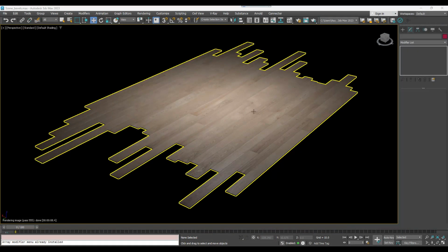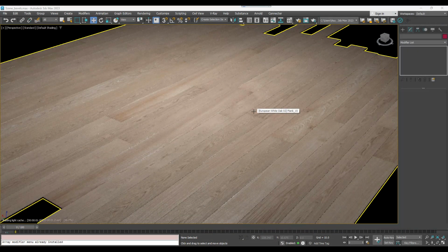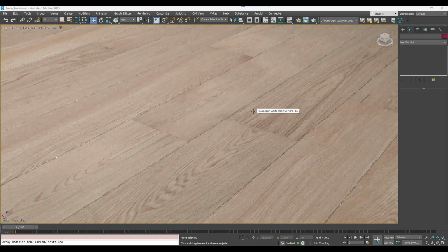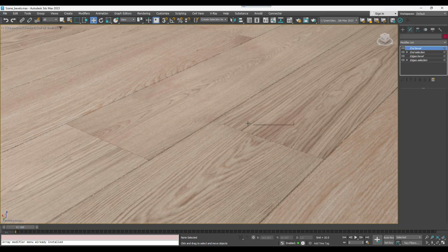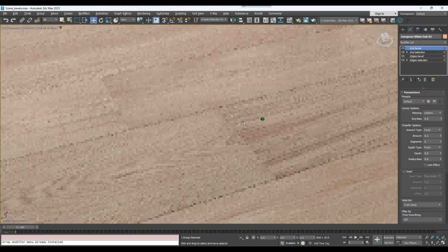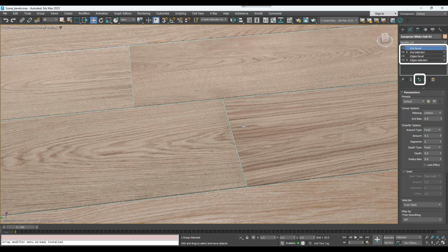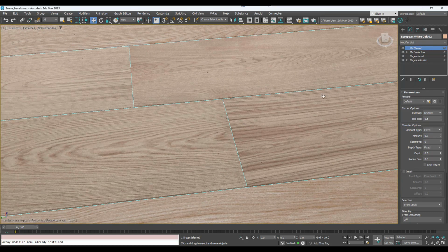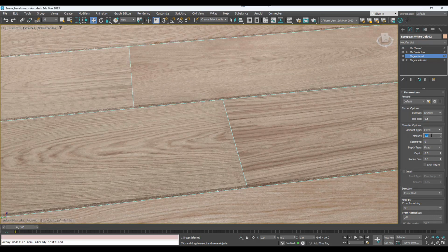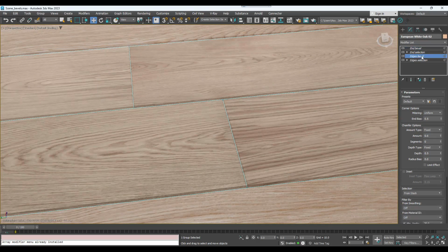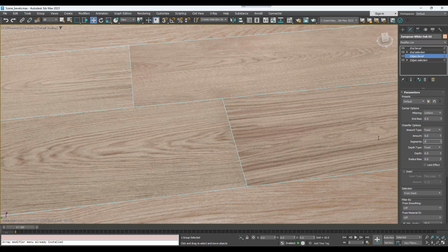The design-connected wood floorings allow you to add beveling to the wood plank's edges and ends. Select the flooring group object and go to the modifier stack. There are 4 modifiers there instanced to all planks in the group. To change the edge or end beveling, simply select the respective modifier and adjust the amount value. To remove the beveling, make the amount 0. You can also turn off the modifier for the end bevel with the same result.